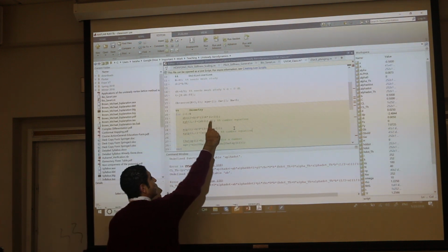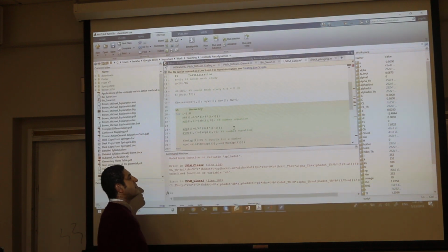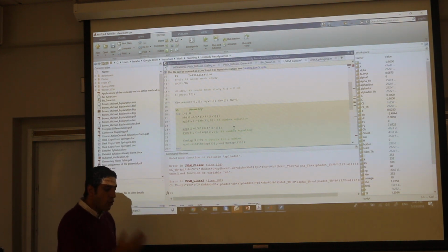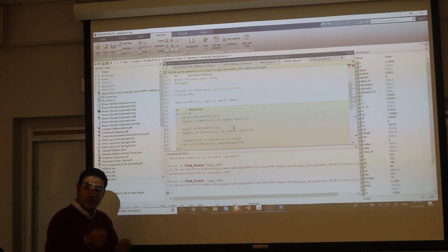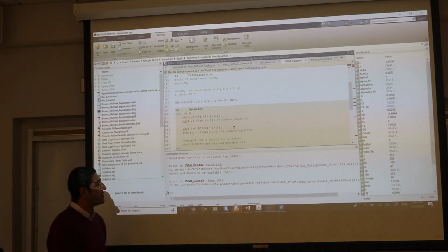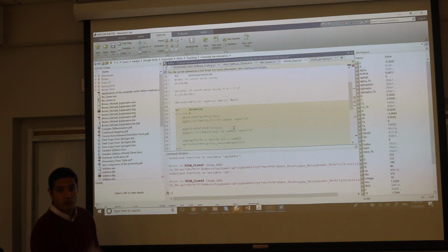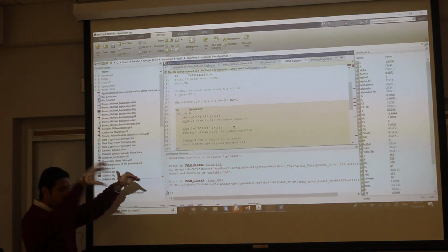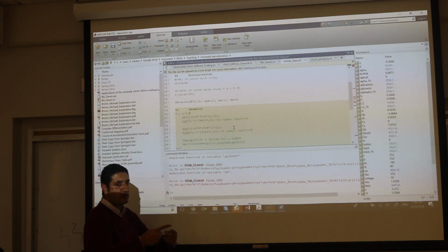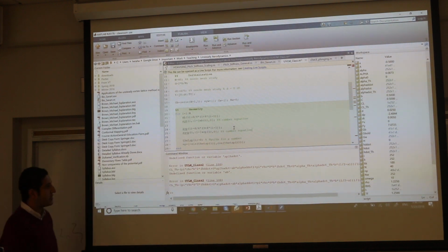So all you need to update is that the y location will be this y plus whatever is coming from flexibility. One of two things: either it's imposed flexible motion, you're assuming it, you have actuators to do that for you. In this case, it's known motion, so you just add it like here. But if it's just natural flexibility coming from a structural model, you have to solve the structural model simultaneously. So your time simulation will call the structural model and will do the aerodynamic model. At the beginning, you initialize it with the rigid case, but then as you move forward, you call your structural model, get the new deflections, and update it as you go. Okay.